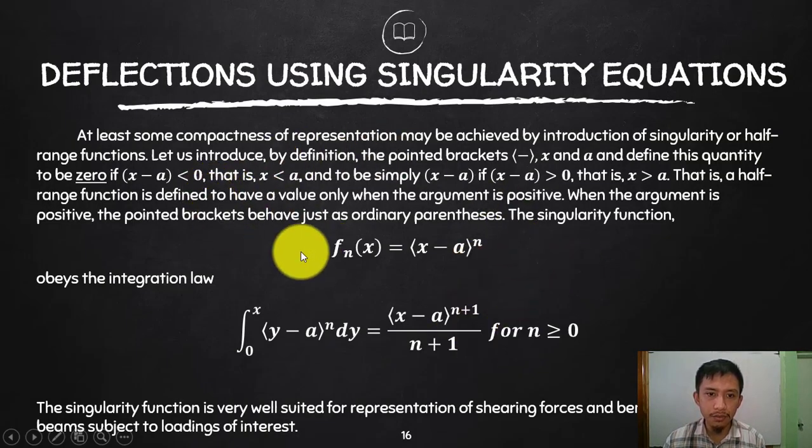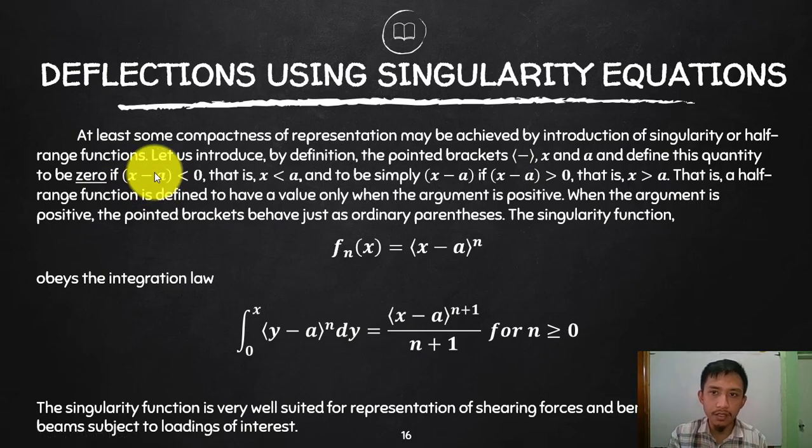We are going to do the same thing: cut the section or segment, get the moment in terms of x, cut the second segment, but this time we are going to put this into a single equation. However, there is a limitation of this equation wherein we establish an equation of x minus a constant, just like what we had before, x minus a number due to the distance of the segment.